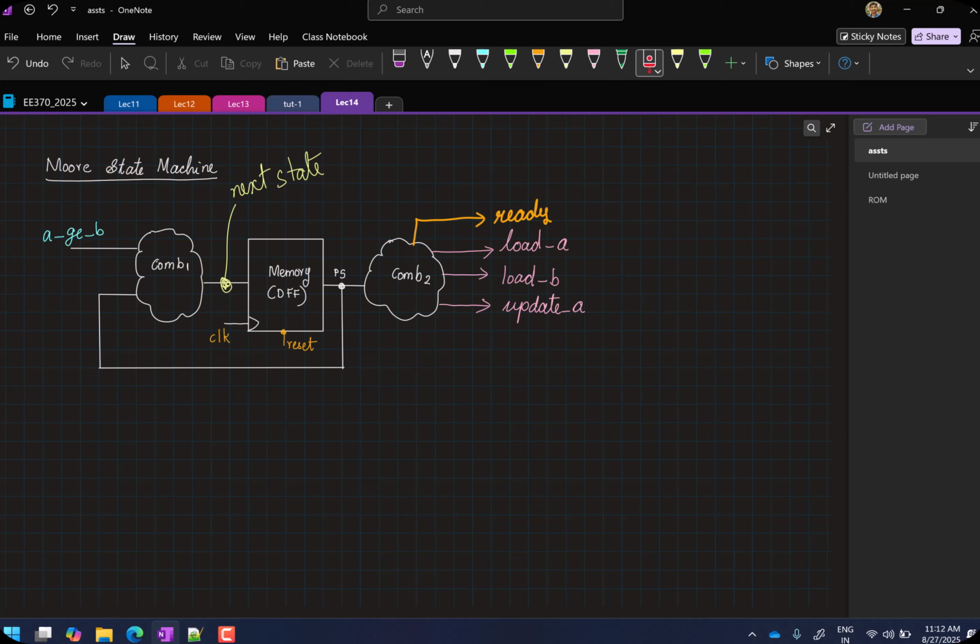Wire, because it is a combinational circuit, right? But you can also implement a combinational circuit even if you declare next state as a register. So it depends on how complicated this combinational circuit is. If you would benefit from using a lot of if else if conditions, or from using a case statement, then it makes more sense to declare next state as a register and then do always @(*) and define the behavior of the next state variable.